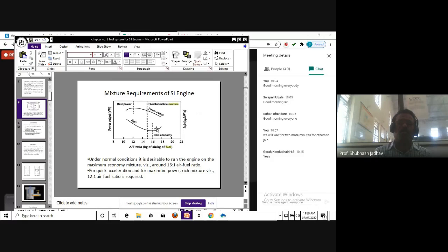So on a higher speed you go or on the lower speed you go, you will have the consumption to be more. That is why you are preferred to run in the green range, which is shown in the speedometer. Okay, so preferably for a bike, etc., it will be around 50 to 70 or something in that particular range. That means if you run the vehicle in that particular range, your fuel consumption is going to be lesser. If you run the vehicle at a lesser speed than that, or higher speed than that particular range, that is beyond the green range, on the lower side or on the higher side, your fuel consumption is going to increase.